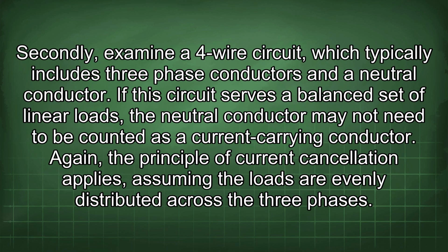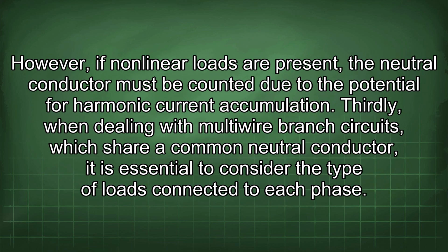Secondly, examine a 4-wire circuit which typically includes 3 phase conductors and a neutral conductor. If this circuit serves a balanced set of linear loads, the neutral conductor may not need to be counted as a current-carrying conductor. Again, the principle of current cancellation applies, assuming the loads are evenly distributed across the 3 phases. However, if nonlinear loads are present, the neutral conductor must be counted due to the potential for harmonic current accumulation.